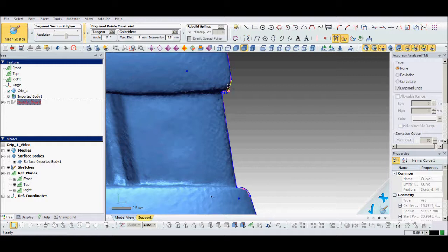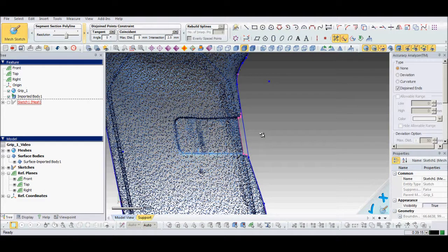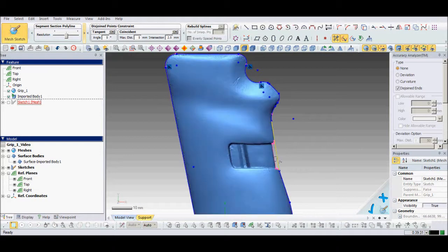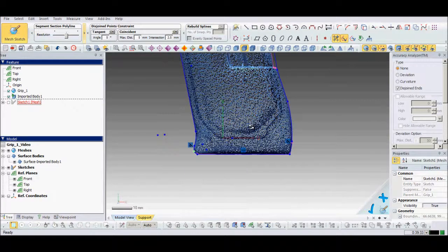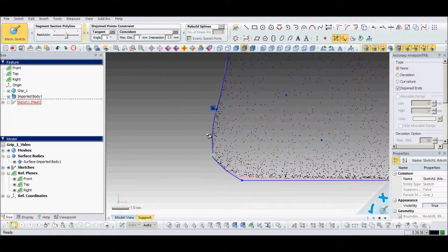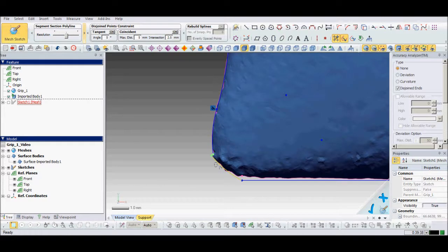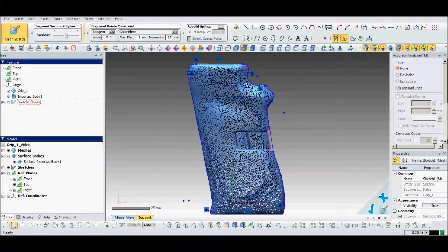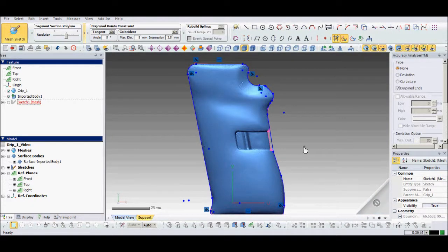So I'm going to go ahead and delete the line, like this, and just for the demonstration, I'm going to pull those together and snap those together. Normally I'd probably, let's pull that a little bit. Let us leave it. So I've gone ahead and deleted this little notch cutout because I don't want that to show in my solid yet. And I have a little bug down here where these two lines didn't quite come together. So I'm going to fix those and bring this all the way down to there and drag that down so it looks a little bit better. I'm going kind of fast through this part just for the sake of the video. So let's go ahead and finish that off.